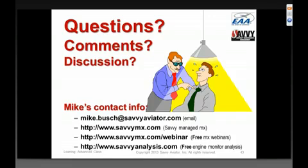Good question. Tom is wondering, how do we know that our engines are approved for operation lean of peak? He's got a Lycoming IO-320. Well, first of all, I don't have to be approved. The only operational things that we have to comply with are in the limitations section of the POH, and as far as I am aware, there aren't any POH limitations with regard to what mixture we can use.